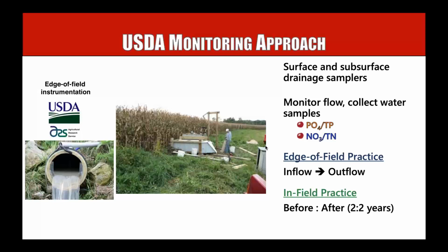And then the way we're doing that, if it's an edge of field practice, like a phosphorus filter or a wetland, there we can do the inflow and the outflow. So the inflow to our management practice tells us what's coming off the field and what's going into that phosphorus filter. The outflow tells us what's coming out of that.